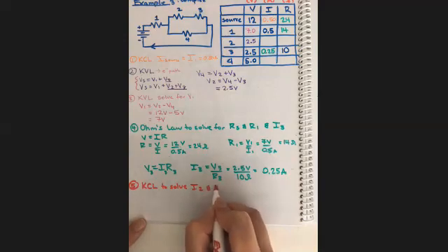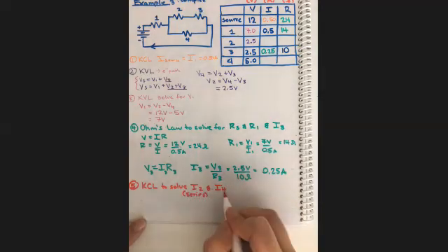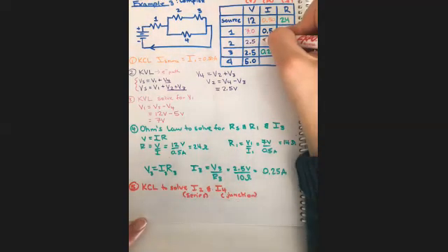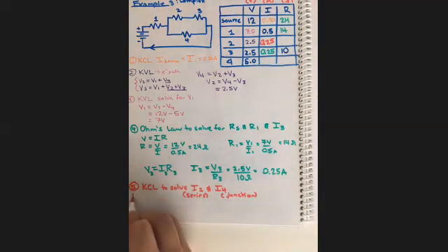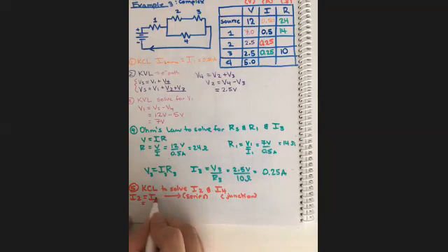and I'm going to use it to solve for I4. But I2 is a series statement. I4 is going to be like a junction, like a parallel. We're going to apply something for parallel. So here I2 is equal to I3 because they are in series with each other. Sorry, this marker is getting fatter as it's used. I2 equals I3, which is 0.25 amps.